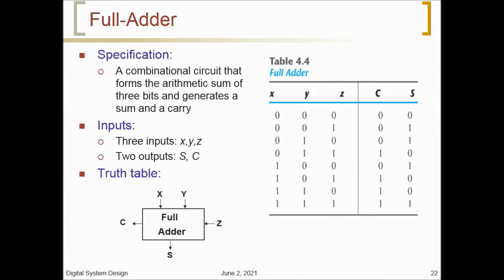The input and output bits of the combinational circuits have different interpretations at various stages of the problem. On the one hand, physically, the binary signals of the input are considered binary digits to be added arithmetically to form a two-digit sum at the output. On the other hand, the same binary values are considered as variables of a Boolean function when expressed in the truth table or when the circuit is implemented with logic gates.